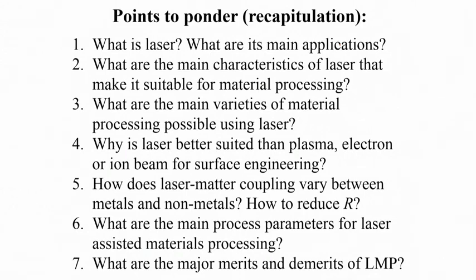So it is an extremely fast process. The other good thing about laser is that the heat deposition profile is exponentially decaying, so there is maximum heating at the surface, and only within a few micrometers from the surface the temperature falls to room temperature. So essentially you are dealing with a very small volume of the solid at a time, and the rest of the bulk will all be at room temperature. So you are affecting a very small volume.